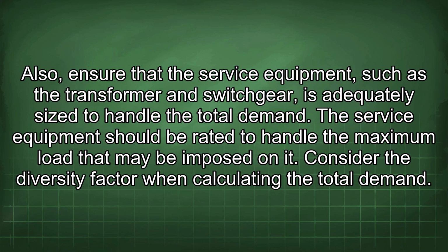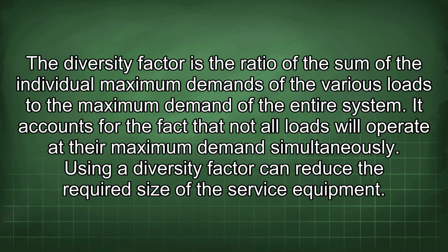Consider the diversity factor when calculating the total demand. The diversity factor is the ratio of the sum of the individual maximum demands of the various loads to the maximum demand of the entire system. It accounts for the fact that not all loads will operate at their maximum demands simultaneously. Using a diversity factor can reduce the required size of the service equipment.